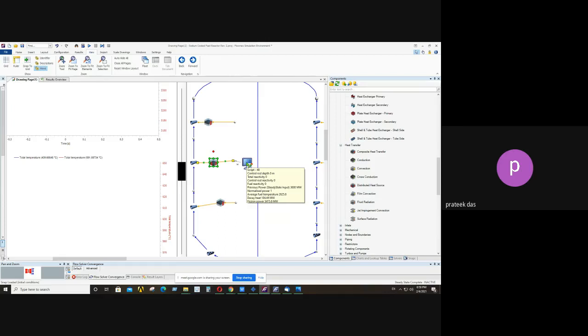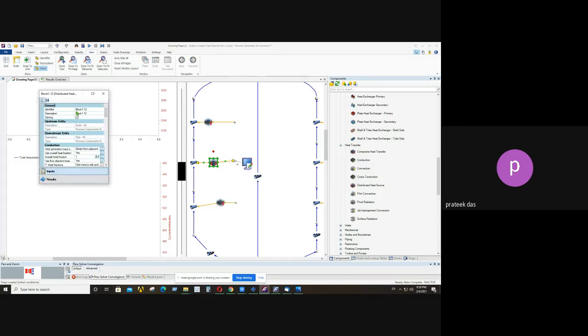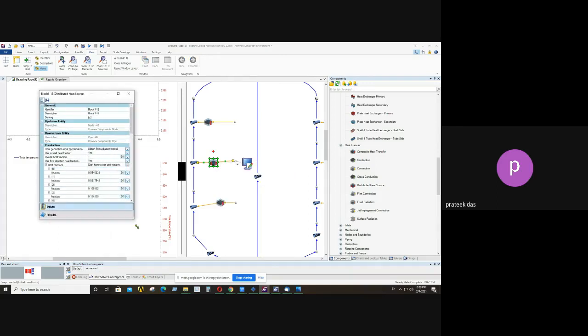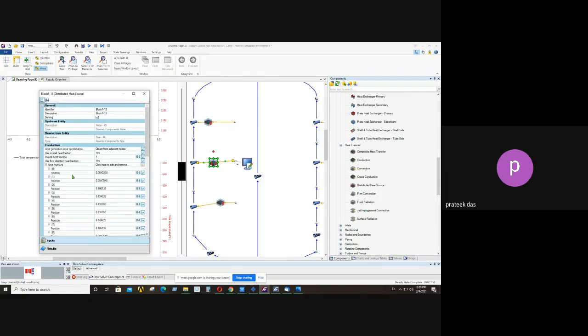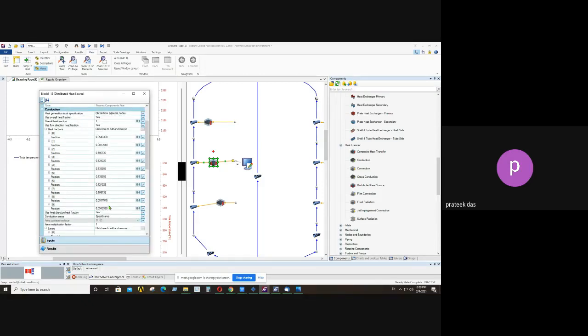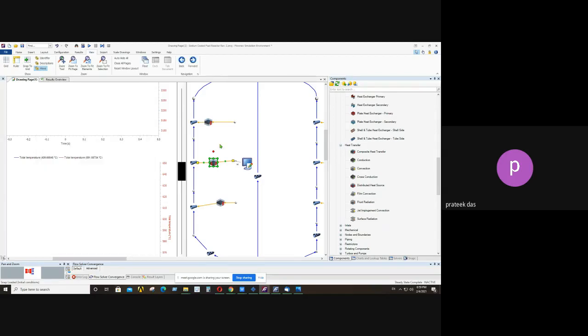According to those zones and the amount of heat generated from each zone, they factorize that and utilize this component to model it. Instead of acting as a single unit source, these fractions are used to represent the different geometry of the reactor, and from those different geometries, varying amounts of heat are generated, and that heat is fed to the cooling medium, in this case molten sodium.